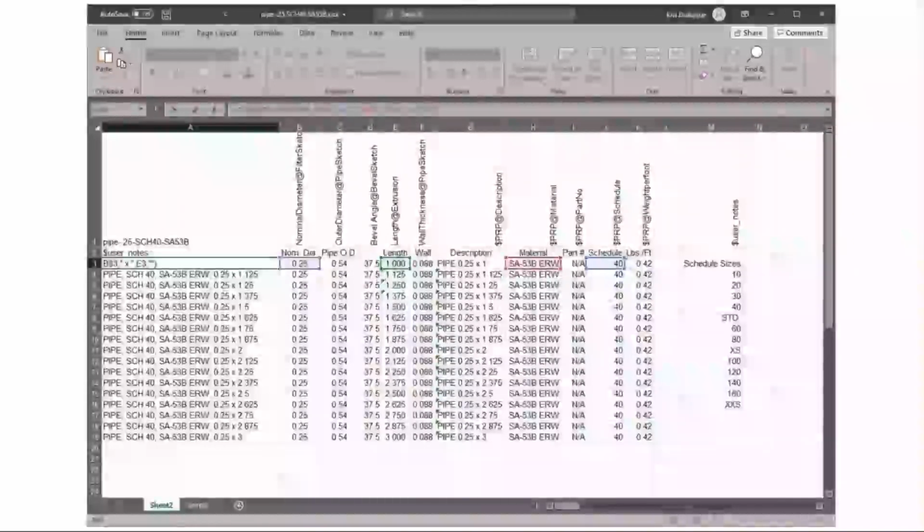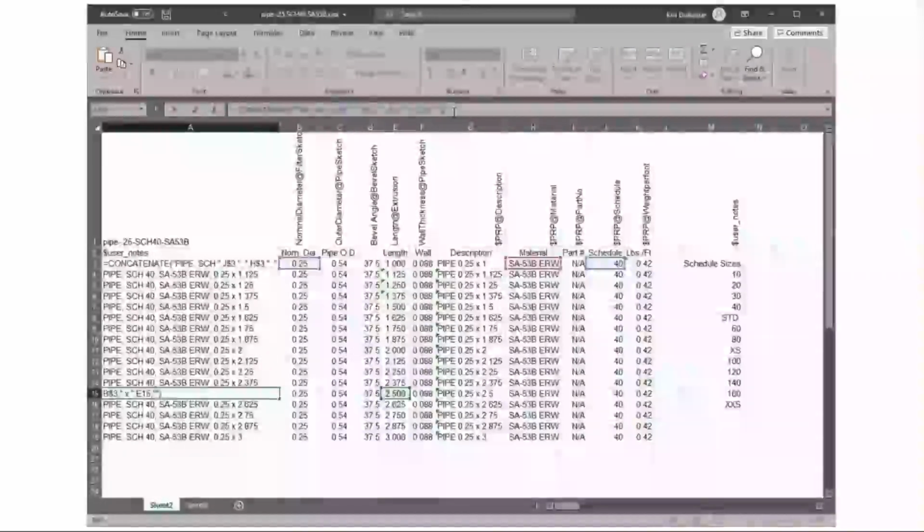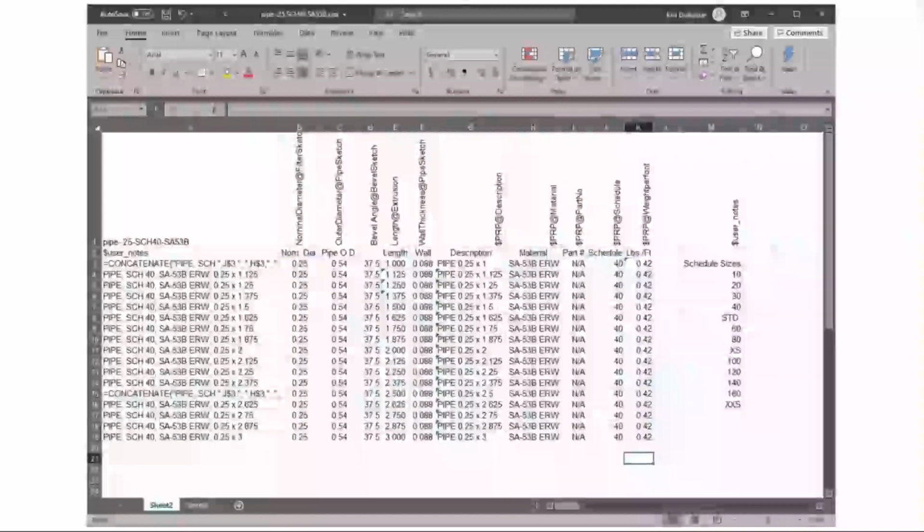And again, we can just copy and paste that information and change the one cell in the length field that's unique. This one is linked to 2.5 inches versus 1 inch. So it really speeds the process up. It's not overly difficult. It can just be time consuming to generate dozens and dozens and dozens of configurations. And I guess I made a mistake. I'm only building a total of 17 configurations, not 20 here.